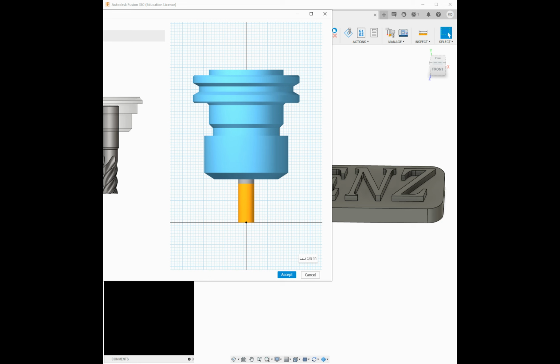And now this is where you would need to do a little measuring. If it's a straight diameter, it's going to be 0.125, but sometimes we can use a larger shank and do what's known as a step down. It provides a little bit more strength. Our shaft diameter is actually going to be the same, 0.125.